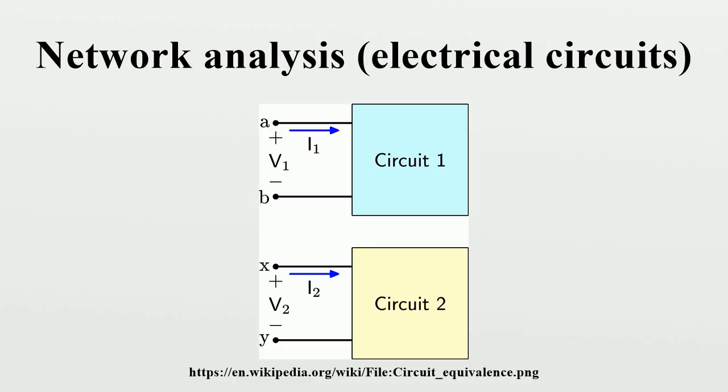Note that mesh analysis and node analysis also implicitly use superposition, so these two are only applicable to linear circuits. Superposition cannot be used to find total power consumed by elements even in linear circuits.